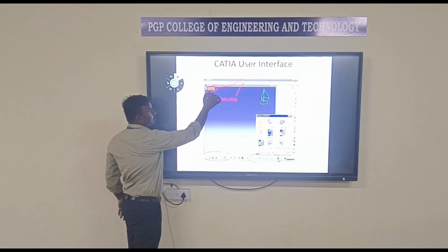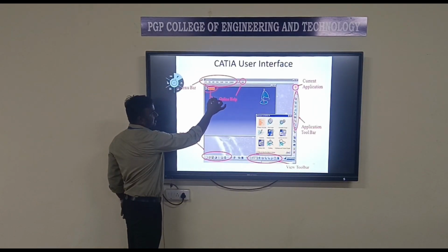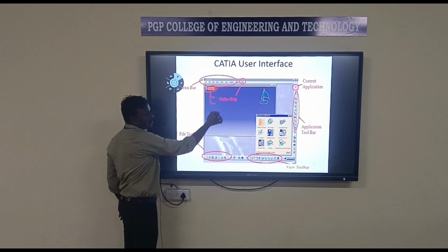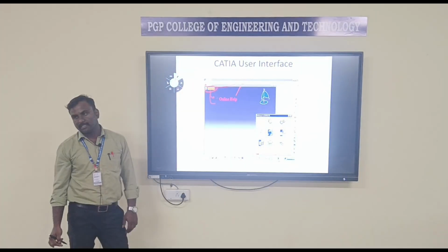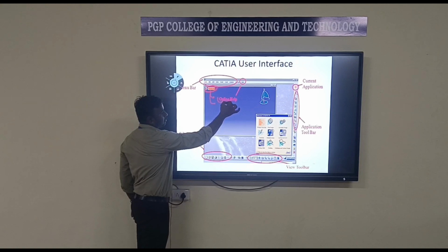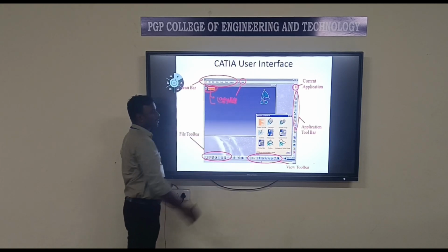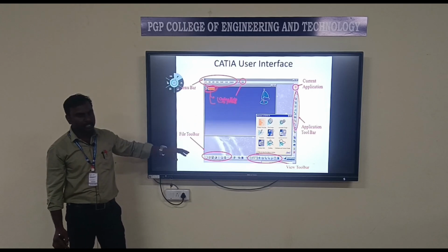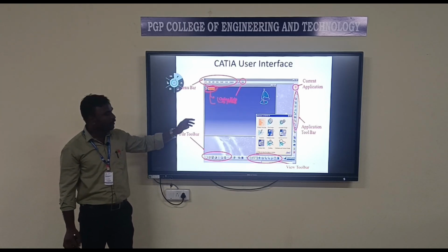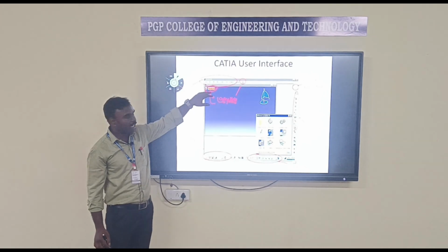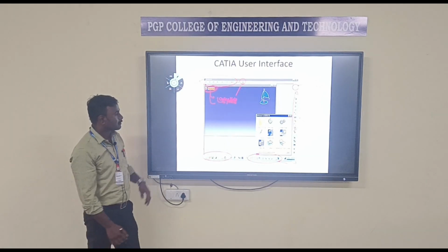You can add a number of products inside beyond this. It's a final product. Product 1, Product 2, those will be called sub-assemblies. Okay. After that, you can add a number of parts. You can add individual parts in this. Okay. So you need not add anything. If you open the CATIA window, it will be added automatically one by one.